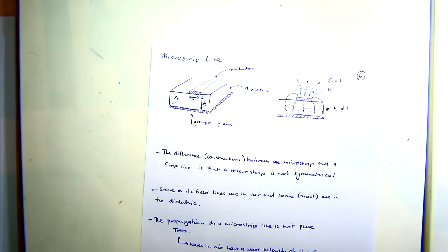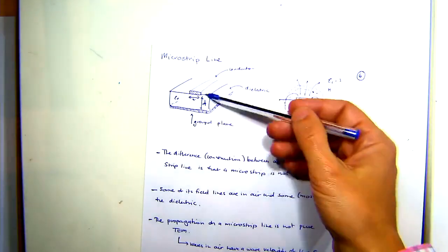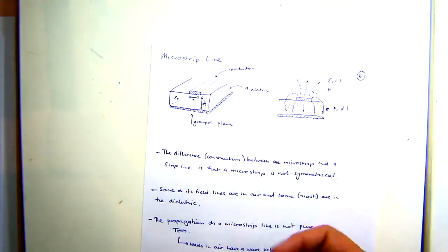You're going to go, well, I want a 50 ohm line. What am I going to do? Well, I can't do a strip line. Maybe I can do a microstrip. Under those circumstances, you'll probably go for a coplanar waveguide. But there are issues with transitions and the like. Usually this is just one of the hands you're dealt, and you've got to play it and see where you end up.